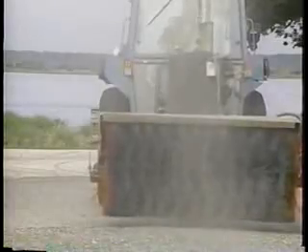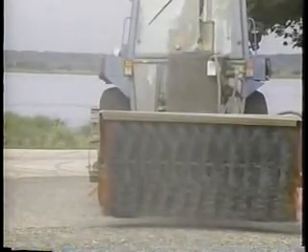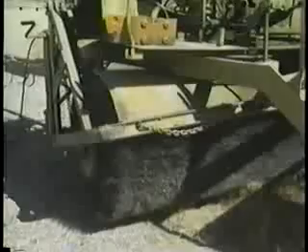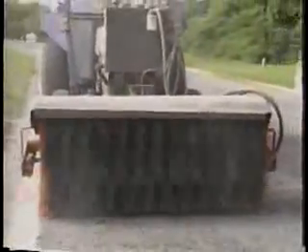At the end of the job, the broom must sweep off any loose chips without dislodging the chips that are set in place. Damage to the fresh chip seal can result from broom bristles that are in poor condition, or from too much downward pressure by the broom. So see that the bristles are long, like this. Stubby ones would more likely dislodge chips from the surface. And be sure that the broom can float. Self-adjust vertically. If it's rigid, there's sure to be too much downward pressure.